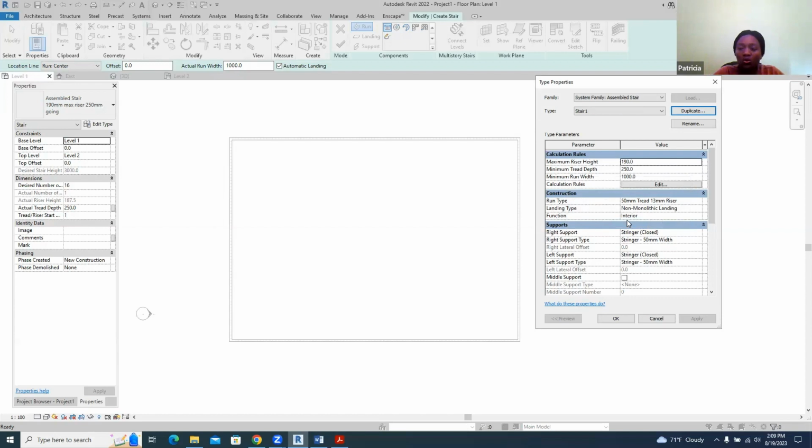From our design rules, we know that we can make our staircase tread, some literature say 220 to 300. I'm saying 190 here. So usually I'm saying that it's 250 to 300 here. So let's say I'm making it 300. And then the riser height should be about 150. I've seen as high as 175 and up to 190. So let's say 170, 150. So this is like your comfortable stairs. Once we set the riser height and depth, it will help us calculate it.